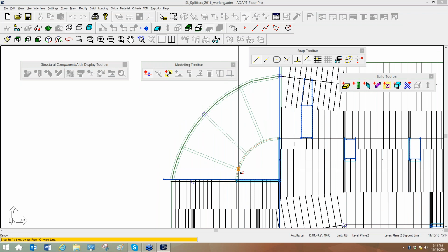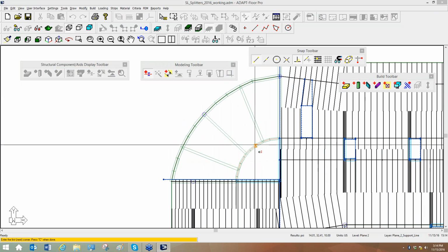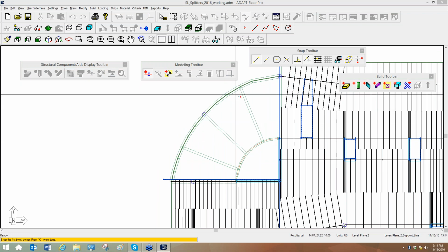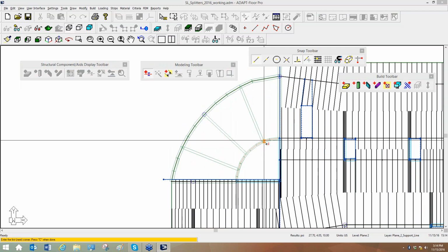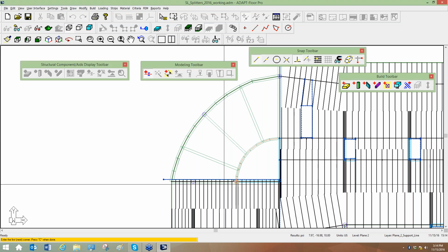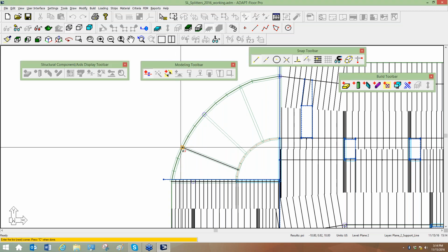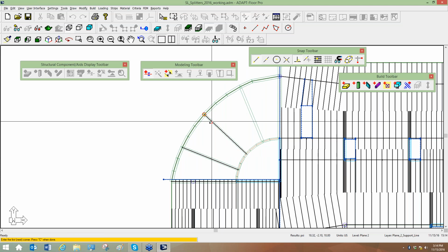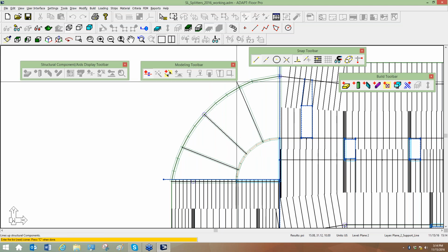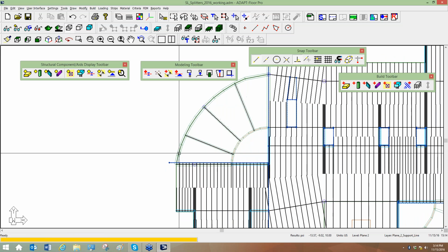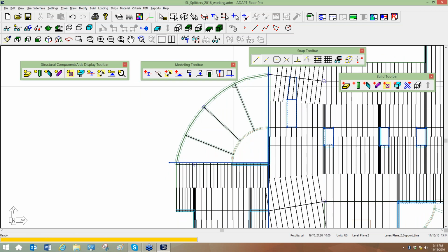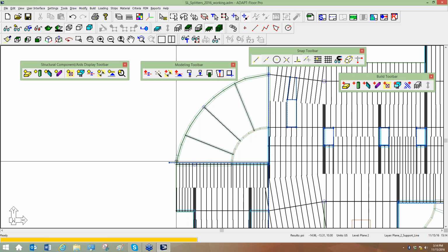This is still X direction. So even though this is aligned almost vertically, it's closer to vertical than it is to horizontal, we're still calling it X direction. And so I'll create a support line along that path, along there, and along there. The support lines touch the edge of a slab on the top, so I don't need any splitters there.